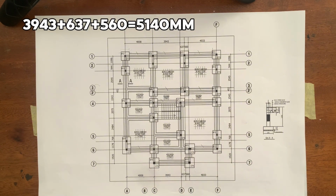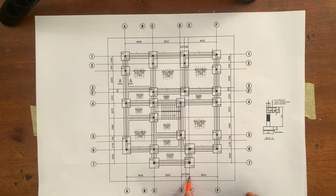So 3,943 plus 637 plus 560 is going to give us 5,140. So the dimension from here to this center line is 5,140. So we can now minus half of the column bases to get the distance for our trench.